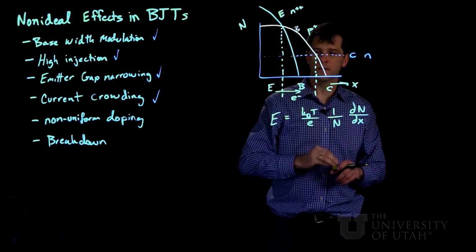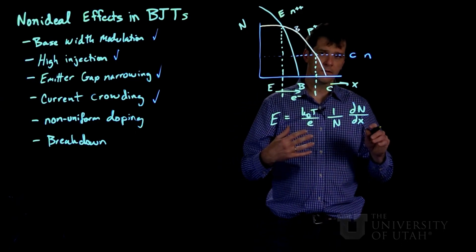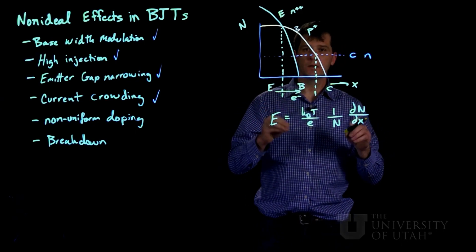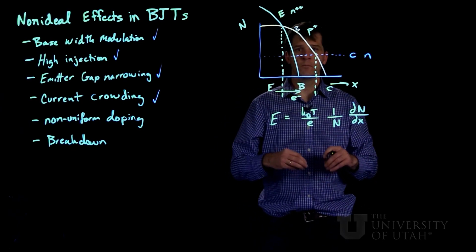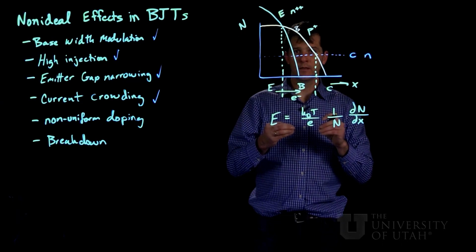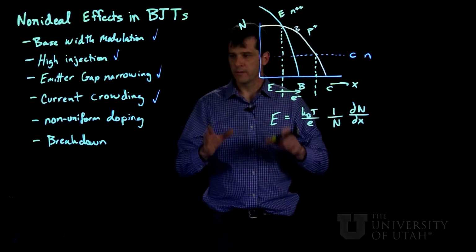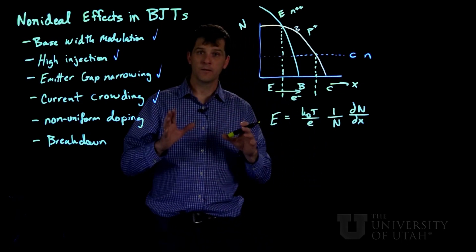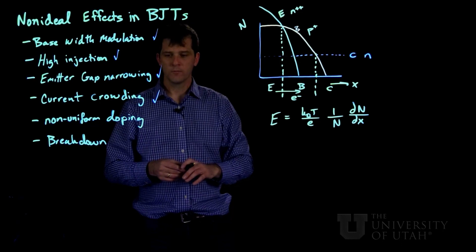So the fact that in many cases these BJTs are constructed by ion implantation during CMOS compatible processing actually means that they can have a higher base collection efficiency, and thus higher gain than they would if the layers were made uniformly doped.